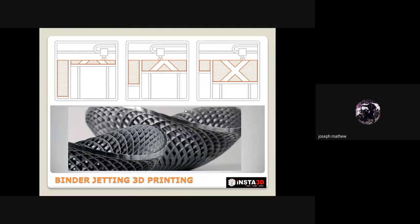So in this, as you see in the image, you will have metal powder which is suspended in the bin, and a roller rolls the powder. Metal powder, sand, anything can be used in the binder jetting 3D printing technology. And when this powder is rolled over the build platform, the binder is applied as per the contour or cross section of the 3D printed component, so that the final 3D printed output is obtained.